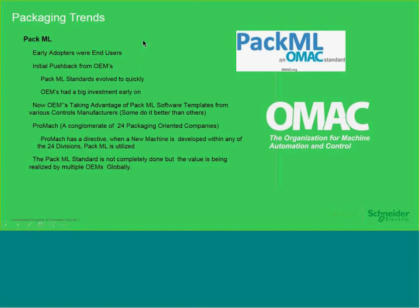We can do it in two ways. With the InduSoft Machine Edition software, there's a PackML screen that you can use to take an existing code and make it PackML compliant by selecting the different variables or tags you want to replicate the different functions within PackML, or you can use a library that we have in our software that, when you first write the code, you can make it PackML compliant. But different OEM organizations such as ProMach, every time they build a new machine, they make it PackML compliant.